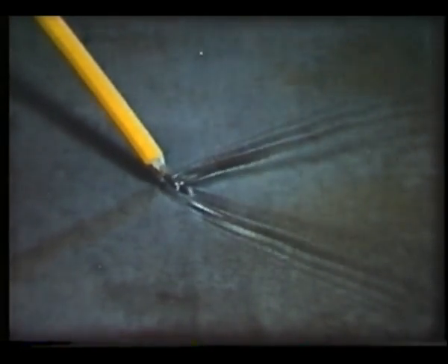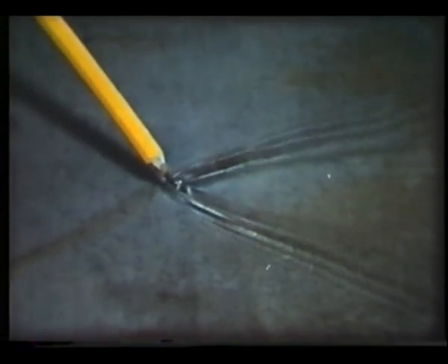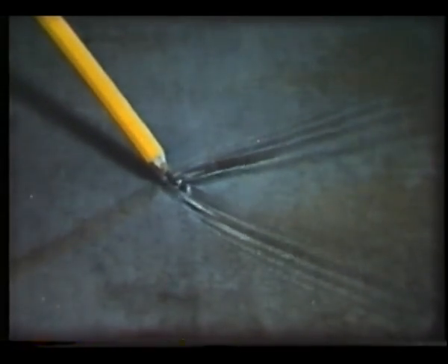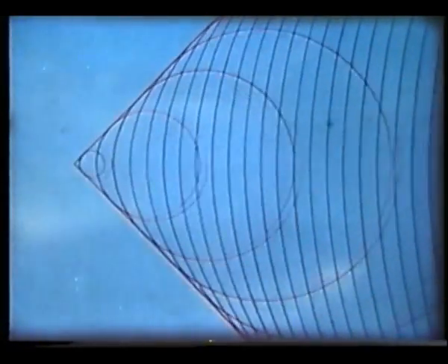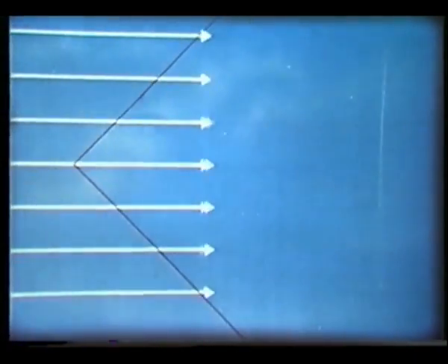The water outside this region flows on as though no disturbance existed. In the same way, the supersonic point can only affect the air lying inside the Mach lines, shown here in white. Ahead of the Mach lines, the air is undisturbed. Since all the disturbances coming from the point are infinitely small, the speed and direction of the airflow, shown here by white streamlines, don't change as the air passes through the Mach lines.